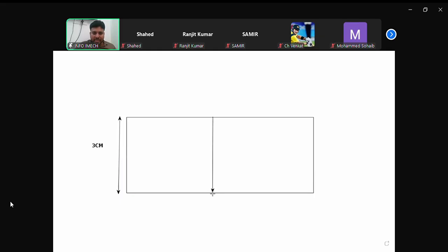It touches here and reflects back. At what distance is it reflecting? 3 centimeters. So the first echo is at 3. The second time also it reflects from 3 centimeters only. In between it is not reflecting. So 3 plus 3, how much? 6. That's why the second echo is at 6.